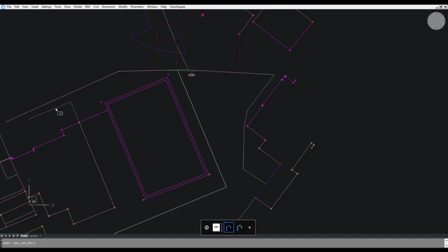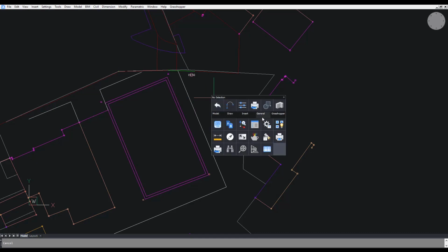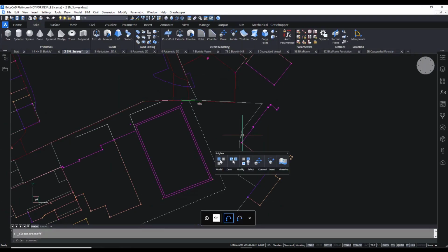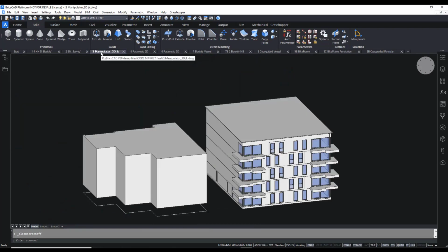Need to rotate, copy, move, or mirror drawing elements? Just hold the pick button a bit longer and the manipulator appears. It offers all the standard copy and displacement commands without a command input. The manipulator can be used with both 2D entities and 3D solids.